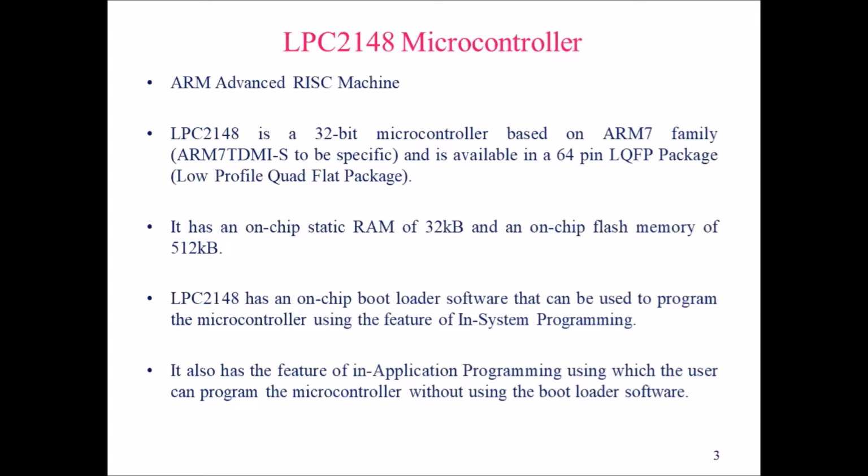LPC2148 is a 32-bit microcontroller. It can handle up to 32-bit data at a single time. It is based on the ARM version 7 family, so it can be called ARM7TDMI. ARM, then 7 is the version. T stands for Thumb instruction, which means that in this ARM version 7, even the Thumb instruction can be executed. It is available in a 64 pin LQFP package.